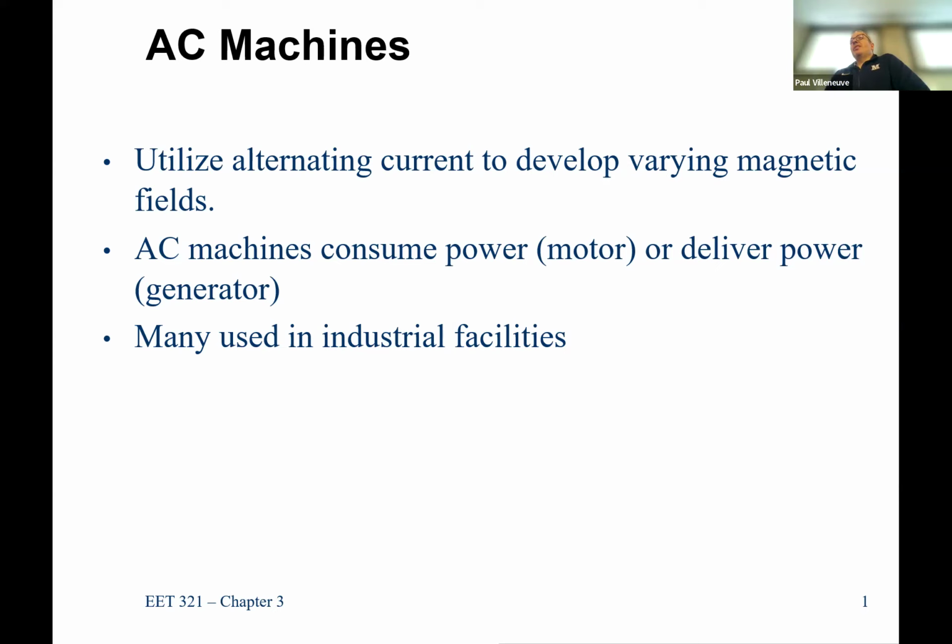Some of the biggest DC machines you'll find tend to be for conveyor systems. If you're moving a lot of product up and down a conveyor, using a DC machine works really well because you can apply a braking force on it and maintain its position. With AC machines, you can brake, like physically slow it down, but maintaining a holding position is much, much tougher for an AC machine.